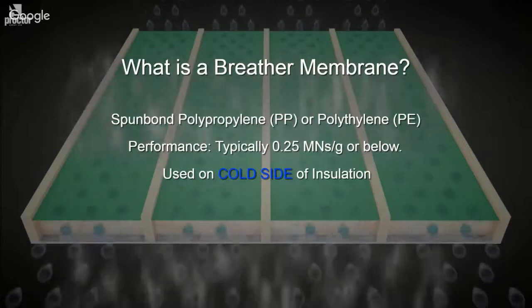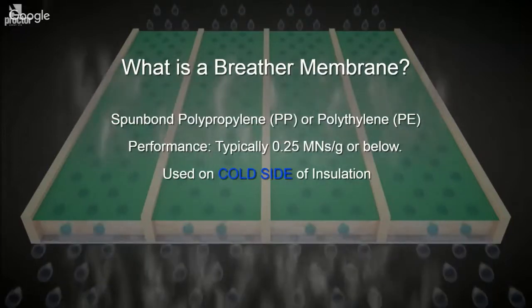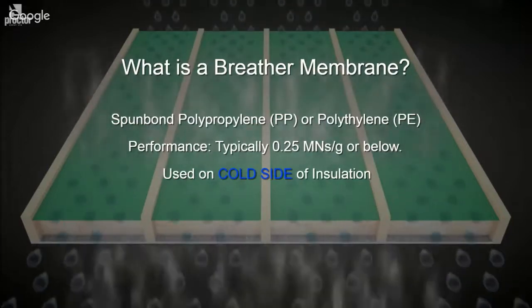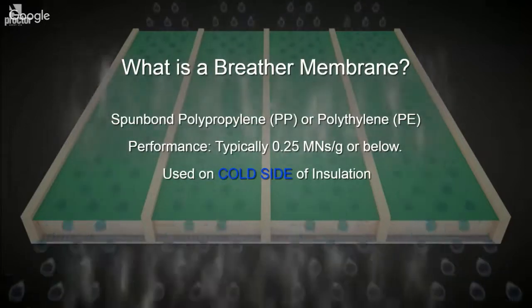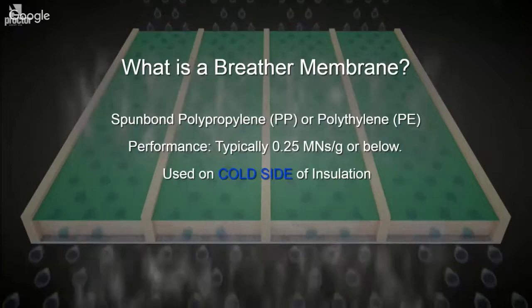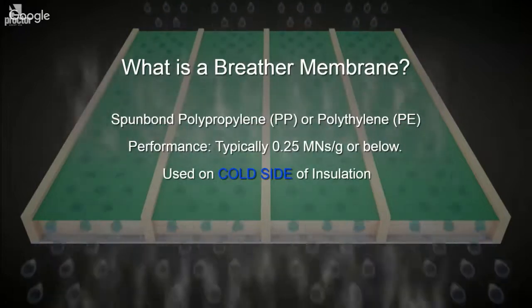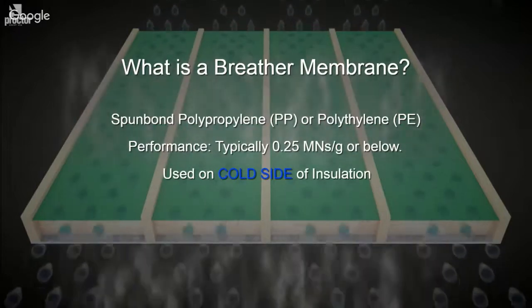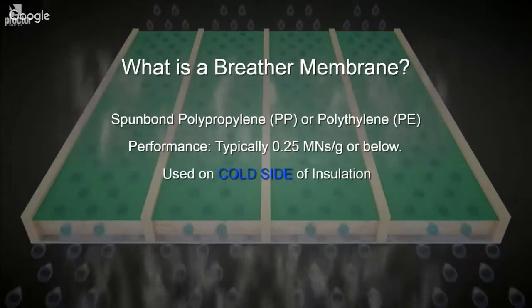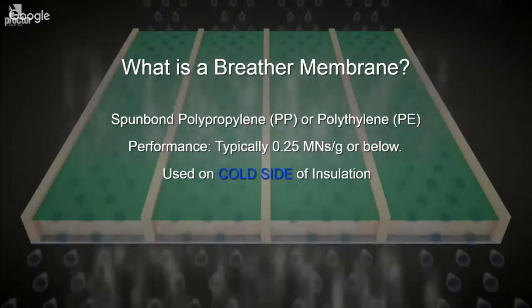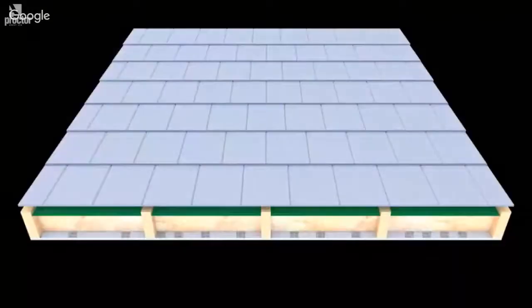Roofing breathable membranes or Vapour Permeable Underlays can be airtight or air open, and that will have an effect on the amount of ventilation, or whether ventilation is required on that particular roof. In the UK, these membranes are always used on the cold side of the insulated envelope, meaning they're always on the external side of the insulation product.